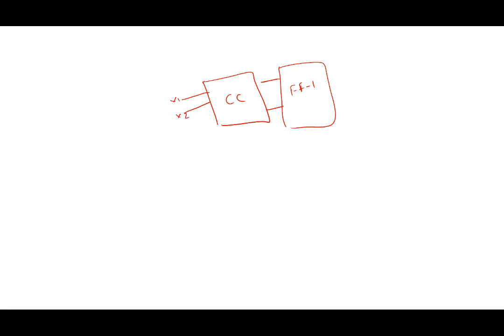So in this particular manner we can take a D flip-flop and convert it into a JK flip-flop. Like that, given any flip-flop, you have a flip-flop 1 and you want to convert it to some other flip-flop. It has some inputs here, so you add a combinational circuit here, CC. This is a combinational circuit whose inputs are the new flip-flop's inputs, let's say X1 and X2, and along with that, you have available Q and Q bar.